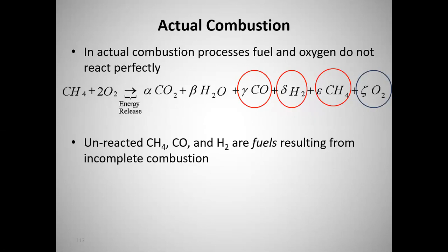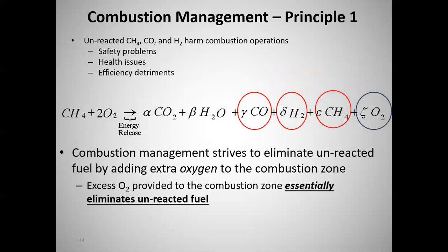CO, you can burn CO. It's not a good fuel, but you can burn it. CO and hydrogen are fuels resulting from incomplete combustion. Okay, so that's not good. You can have safety, health, and efficiency issues. Safety: they can burn in the stack where you don't want them to burn. They're still fuels. You get the right mixture, you can have a fire in the stack. Health: you don't want to put that stuff out. People breathe it. And efficiency.